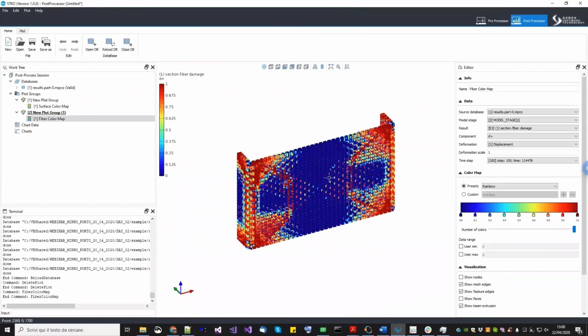Okay, so with this point, I told you about the difference between a thick shell and a thin shell. Just another question. Does it mean we should always use thick shell theory? Yes, for two reasons actually. In case of micromodeling, you should always use the thick shell theory. Why? Because I told you there is a huge difference in the material parameters.